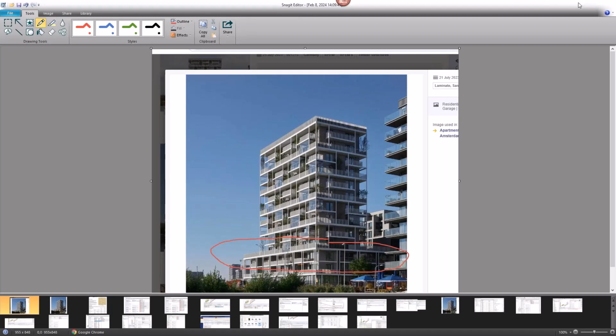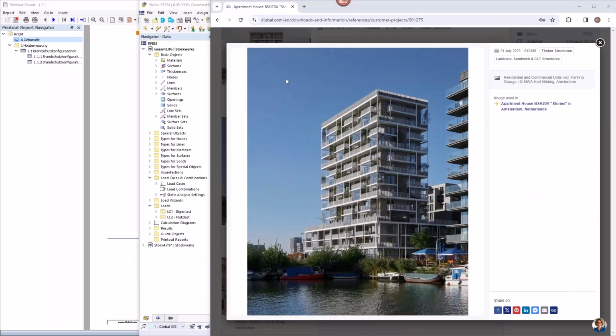So how can you do this? First of all, you can model it in 3D and regard all construction stages analysis, all this stuff in the 3D model, or you can model it in 2D, and then you have to connect each story via the option load transfer. And this is the option that I'm choosing here today.